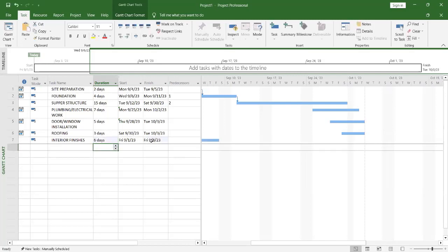Okay, but the interior finishes can actually start. But for the risk sake, we can just decide that, okay, let them finish the roofing before we do any interior finishes, to avoid safety issues. Okay, for safety rules in construction, because if they are doing roofing and other activities are going on, people are up working, and then somebody is down working, it is prone to risk.